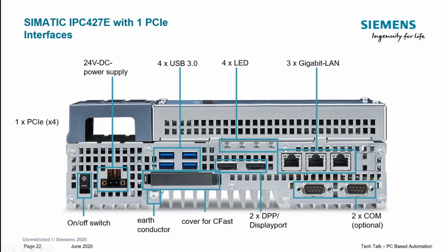Now, one of the big deals with these IPCs in comparison to an open controller is there is no ability to do isochronous real time. And the reason behind that is because these 3 ports here are actually Intel based. So they're not true Profinet controllers as a hardnet controller as such. So it is completely softnet, so it's not actually capable of achieving the isochronous real time.